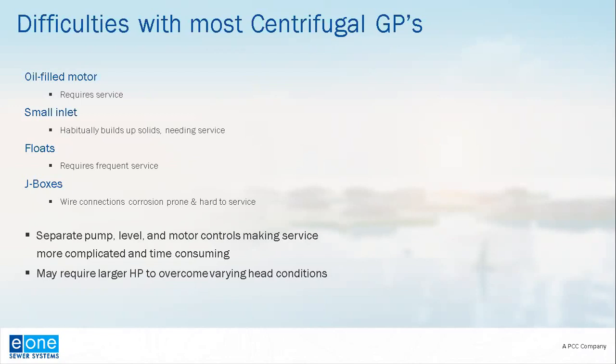So oil-filled motors, we avoid that through our air-filled motor, which is pressed into a casting, if you will, which is located in the wet well of the station and efficiently dissipates heat. With centrifugal pumps, you've got a small 2.5-inch inlet, which is prone to building up solids. And again, if it's a cutter that requires sharpness, which it would in the case of a centrifugal pump, you're going to have frequent jamming.